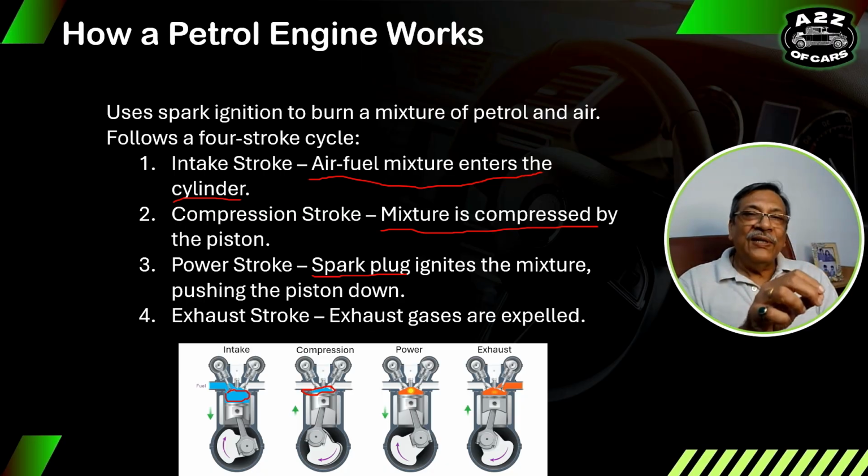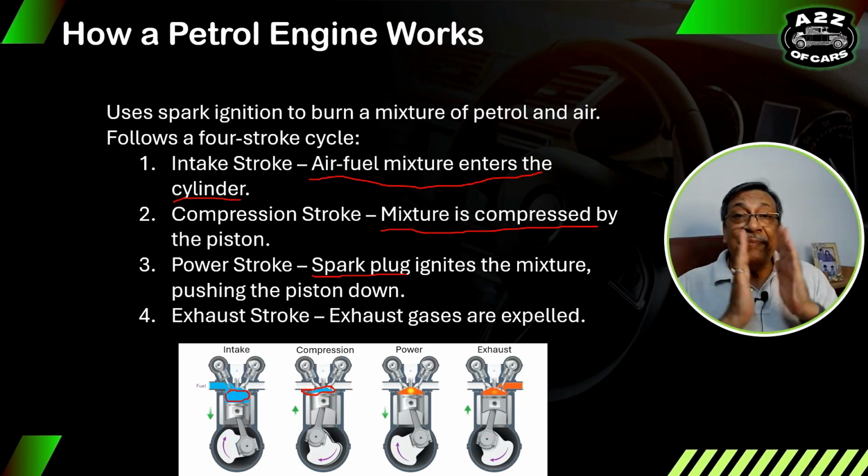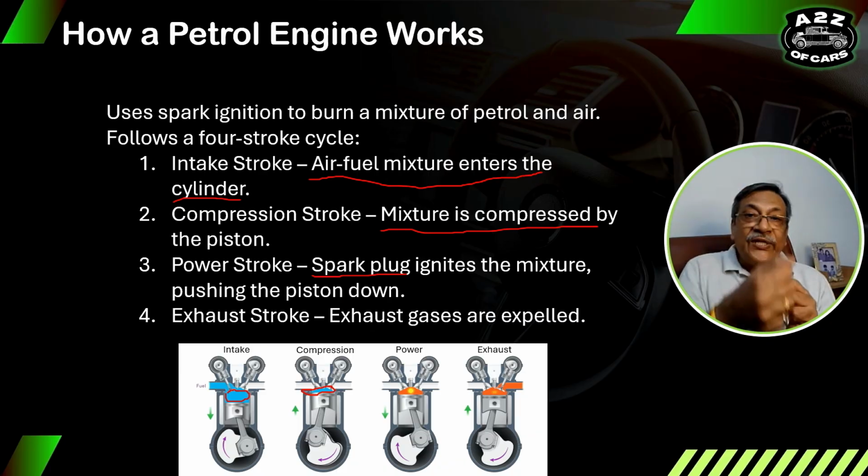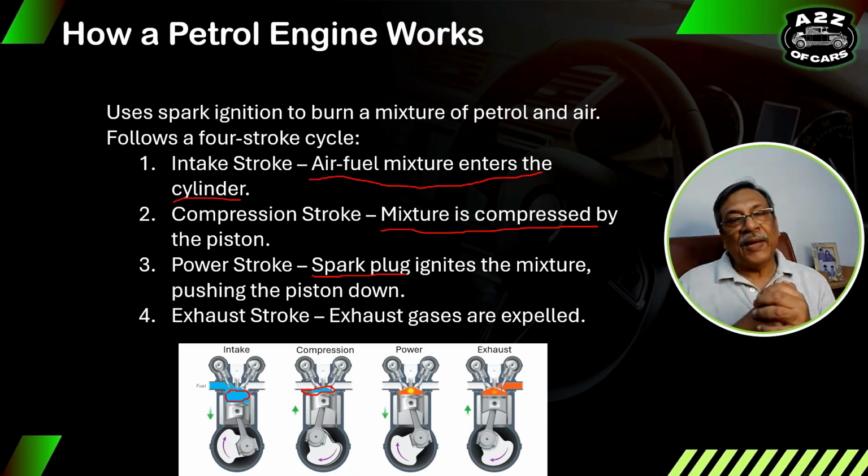So here it is a petrol engine, there's a spark due to the spark plug. And as soon as there is a spark, what happens? There is a highly compressed air fuel mixture inside. What will happen if you give a spark? It will blast, right? And once it blasts, because there is no other space to go anywhere, the energy cannot go anywhere else. So what happens? It pushes the piston down, and that actually creates the power stroke.